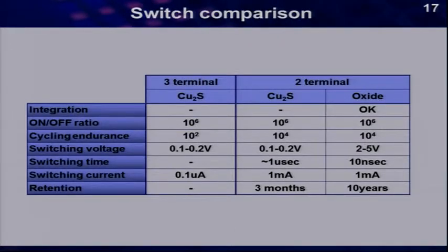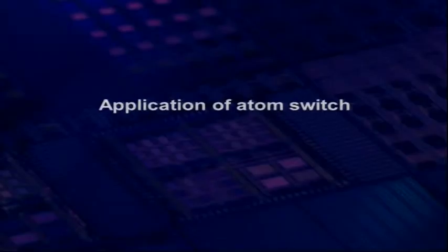Here, again, the summary of the switch properties. By using the oxide ionic conductor, we can successfully integrate two-terminal switch. And we confirm the large on-off resistance ratio and short pulse writing. And let me move on to the next topic of application of atom switch.